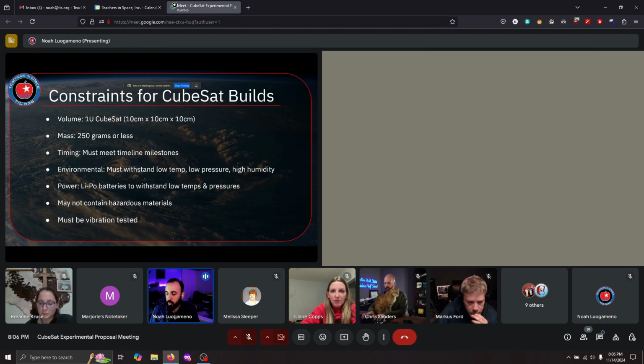It's a really good one for this because when it solidifies, it turns into kind of a rubbery plastic material, which is good because it can absorb vibrations, but also after you've put this all together, if you decide you want to modify or reuse parts from your CubeSat build, this particular type is easy to take off. And again, that's E6000.